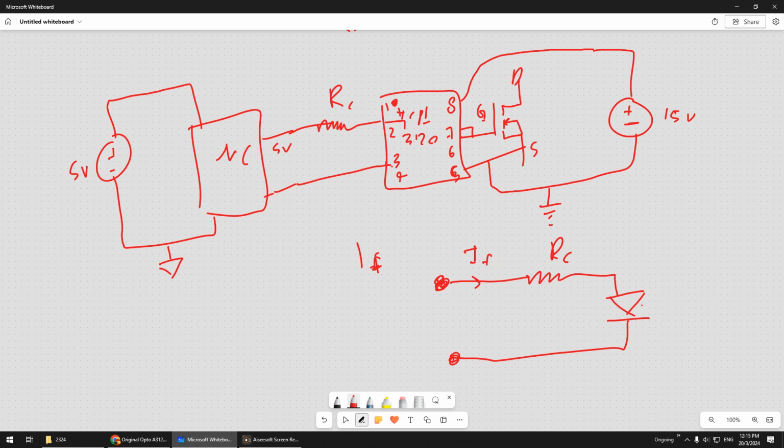To turn on this diode you need 16 milliampere. Okay, and I think much lower, 7 milliampere, and the maximum, if not mistaken, is 30 milliampere. So make sure, 25 milliampere if not mistaken. So make sure when you design this, it needs to be above 7 milliampere and lower than 25 milliampere.